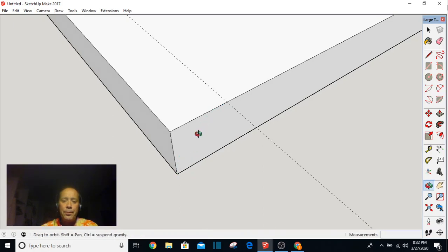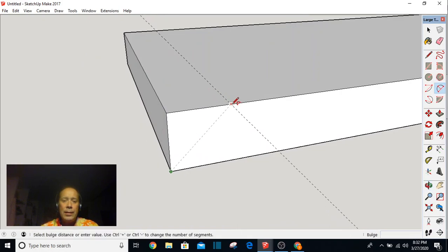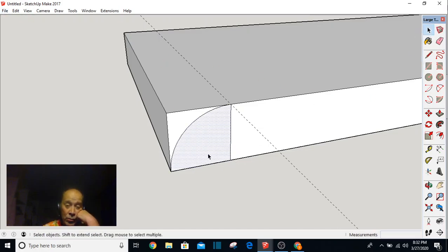Now, this is 3/4 of an inch. That's 3/4 of an inch. I want you to notice what that says. Where is it? It's right there. It says tangent to edge. Tangent to edge, where it changes color like that, tells you that this shape right here is basically 1/4 of a circle.